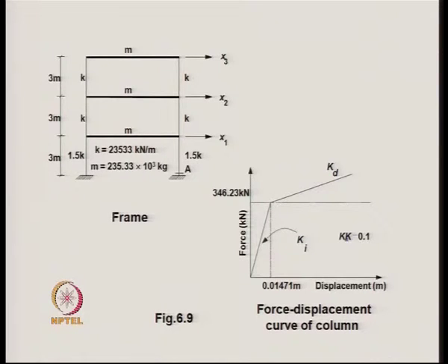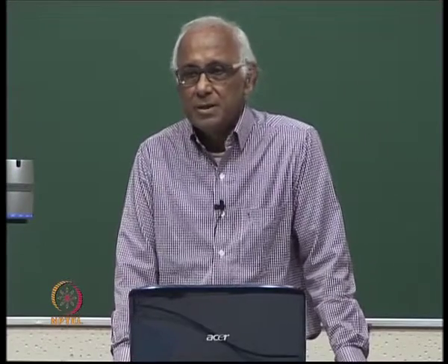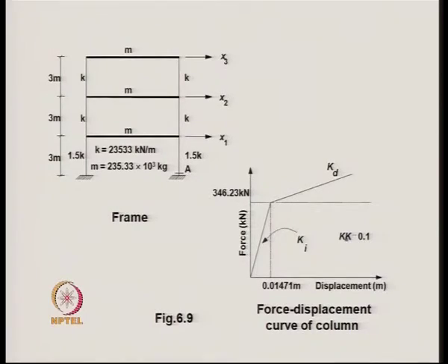We consider that that particular cross section can still take a certain value of the shear force or the bending moment under subsequent loading, but with a reduced stiffness of Kd. In that particular way we perform the calculation.